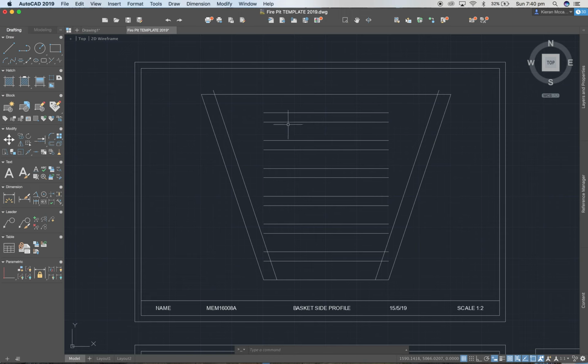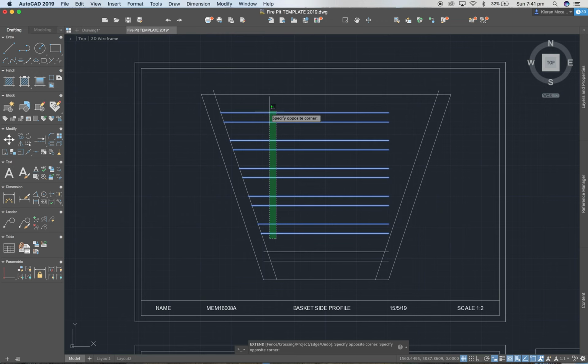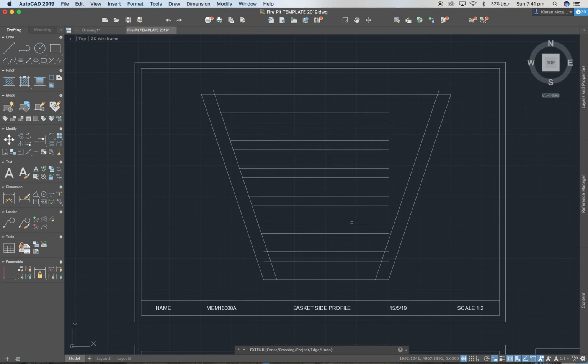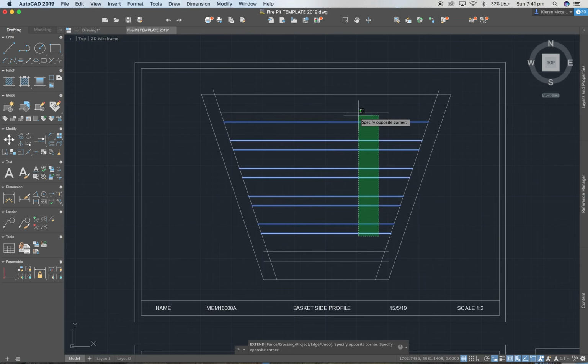Now we're going to use the extend tool that we use down the bottom here. Again, it should be this arrow. If not, remember, select here, onto the page, press enter. I'm going to just click and I'm going to go up the page on the inside here and select all of these to extend, like so, and do the same again here, like so.